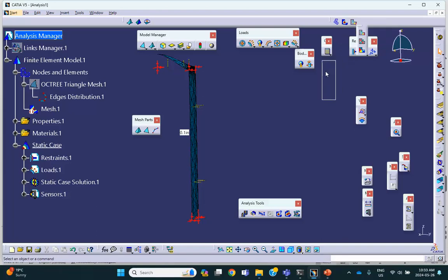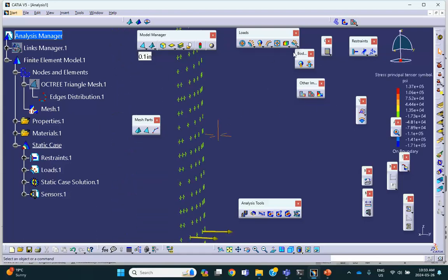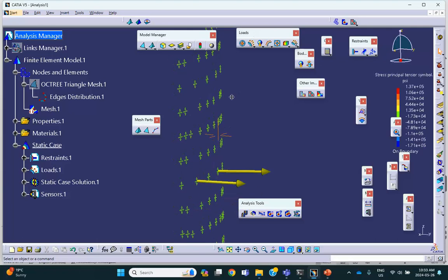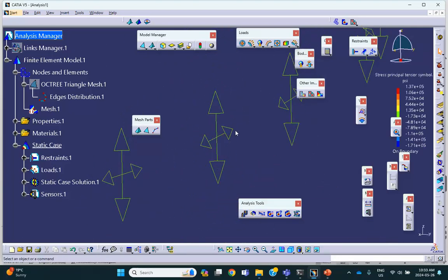Let me get this thing out. These are principal stresses in the form of a symbol. Let's move in. Both are tensile. This must be 2,500. And hallelujah, it is. Sorry, this is the hoop. This is the axial. 2,500 theoretically. It says 2,400. And this one is supposed to be 5,000. It's almost 5,000, 4,760.